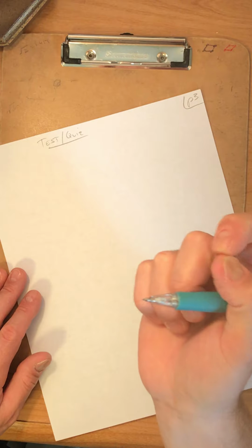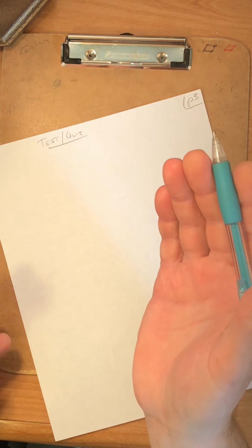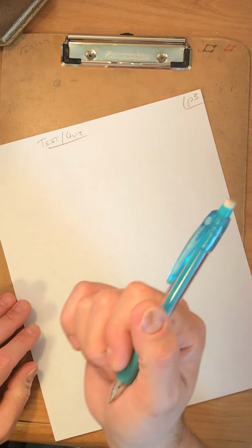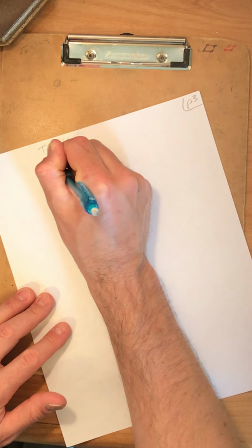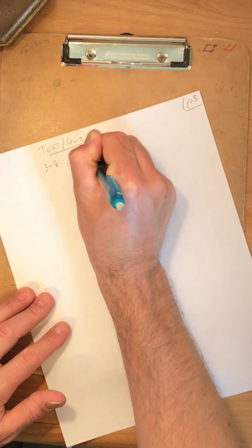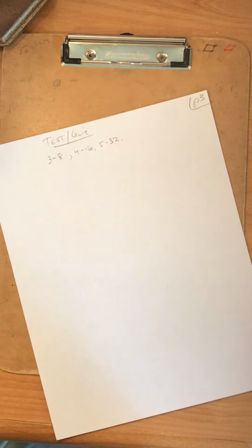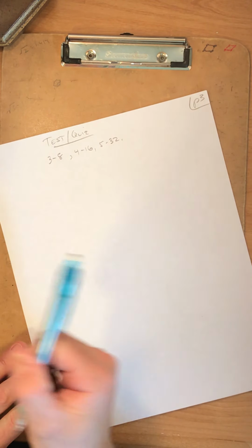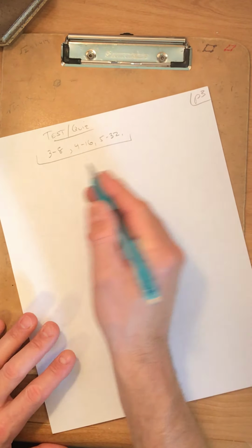We've talked about how the decoder is minterms. Well, we can use this to implement functions. We've talked about 2 to 4 decoders. We could also have a 3 to 8, 4 to 16, 5 to 32. You can also use smaller decoders to build bigger ones, which we'll get to in a moment.